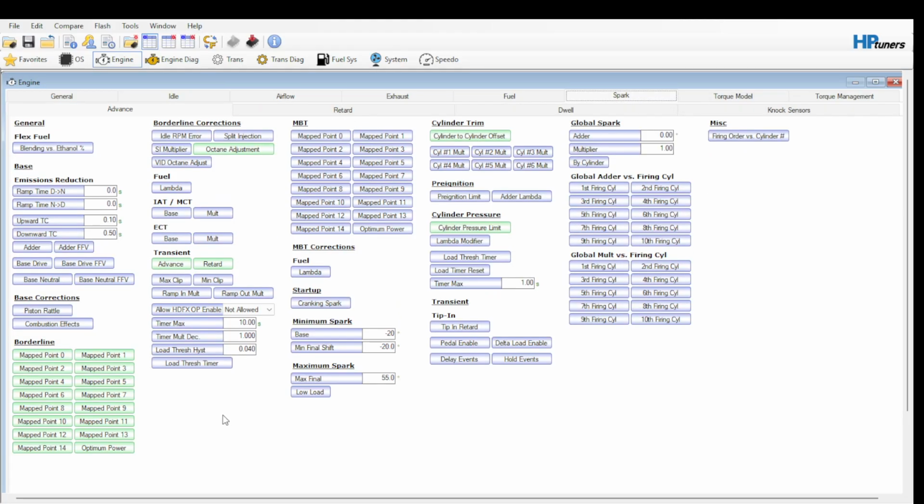But yeah, going back to spark, people like to crank these numbers crazy high. And again, I'm not a fan. I don't particularly care about losing, like I said, even 20 horsepower if it means saving the head, right? Because there's a smarter way to do this too, right? You can get the fuel efficiency back of running on E85, and you also can take the advantage of the higher knock resistance and, you know, increase spark and increase horsepower.